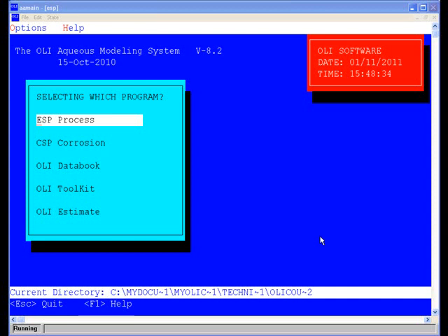This tutorial shows you how to find the buried thermodynamic properties for aqueous and MSC models in ESP. Unfortunately, these parameters are not displayed directly to the screen, but they are saved internally in the program.